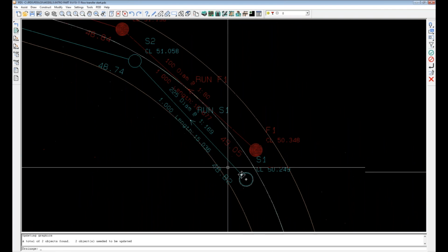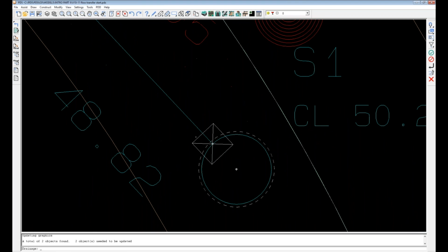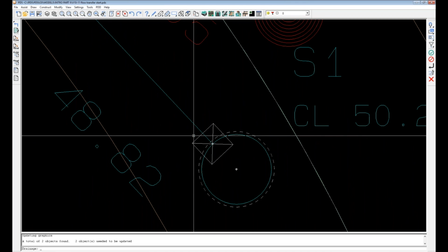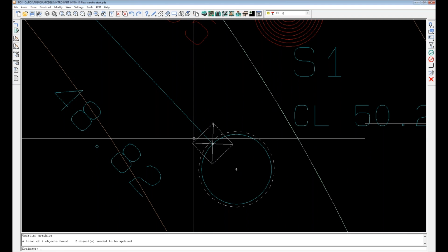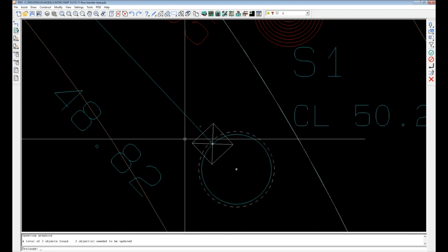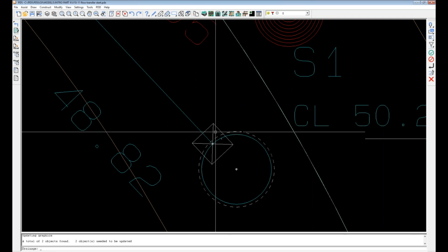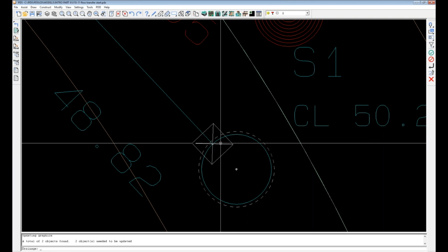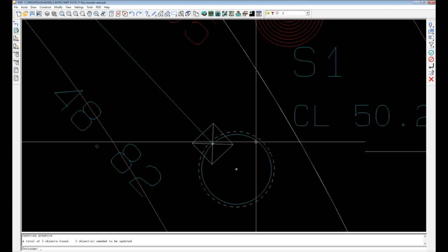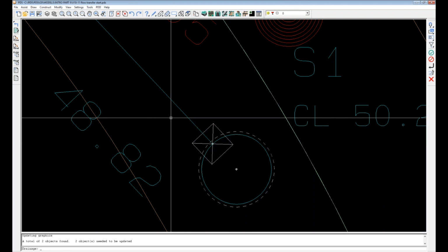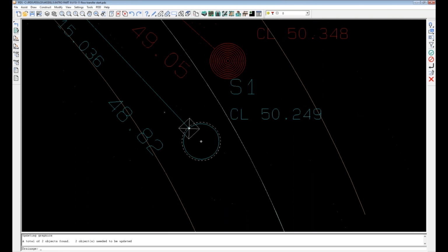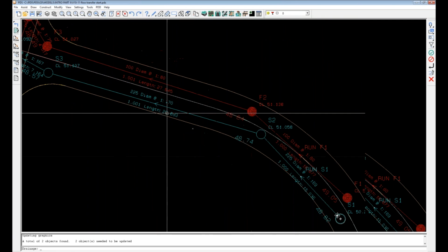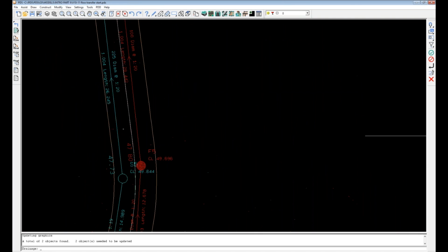Also, what you will notice is that the flow controls are here. The flow controls that Tom was demonstrating in flow are here. You can see them. The same convention is used. The square with the cross through it is an online control. The dotted sort of halo going around the manhole indicates the storage structure. So we're using, again, the same type of convention as in flow.